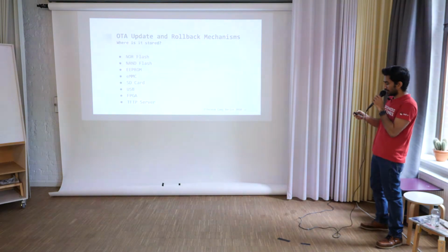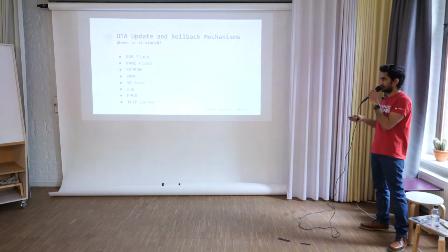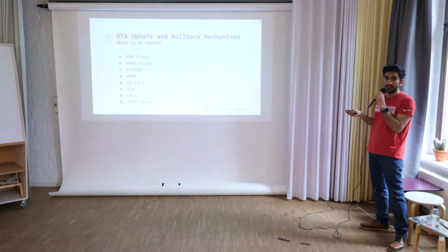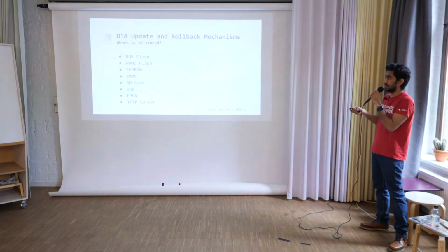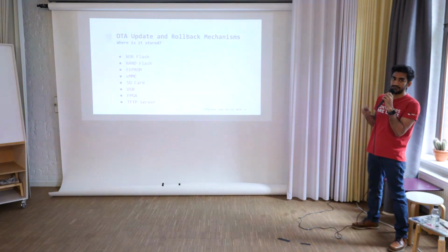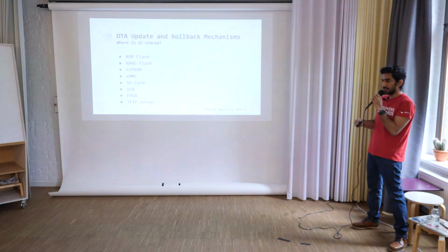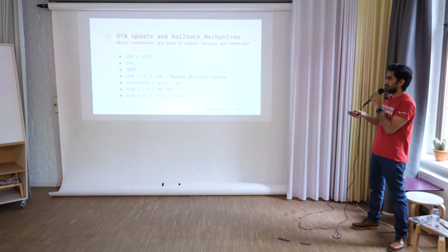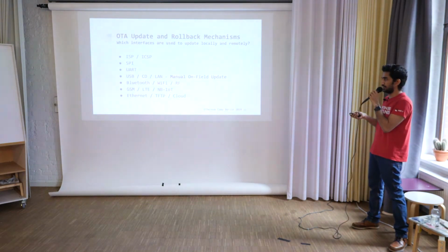Usually the places where the software is stored are different, and they have different file systems. For example, for NAND flash it is UBI, and then you have ext4, and depending on the storage, you have a different package that has to be released. So for the interfaces, usually in system programming, SPI or UART, or people used to update things by manually going there and replacing things.